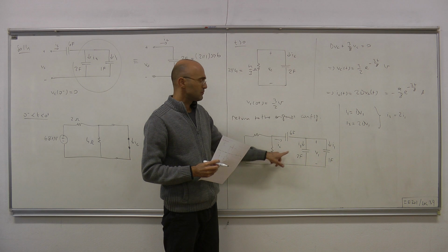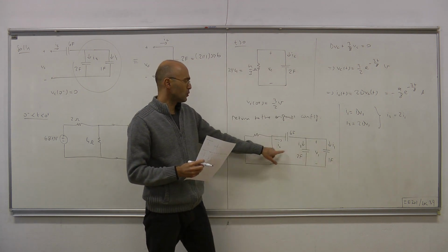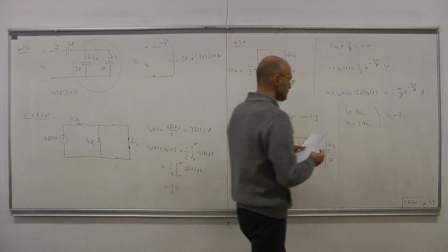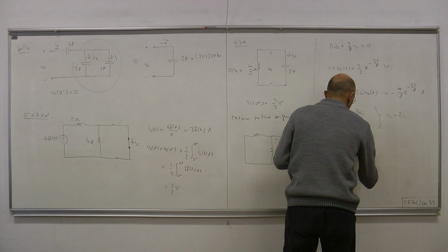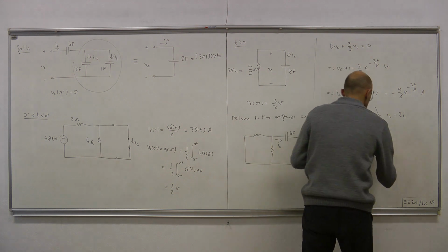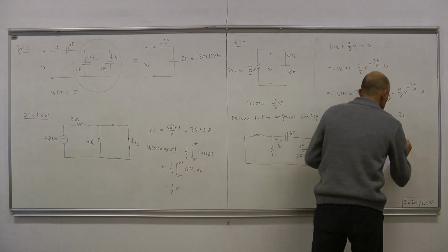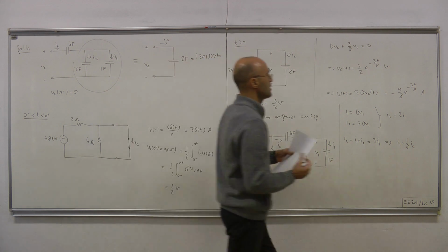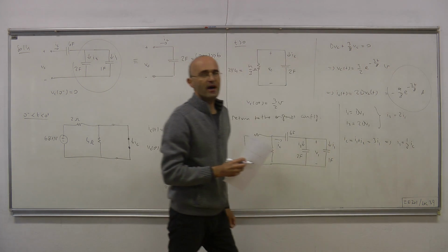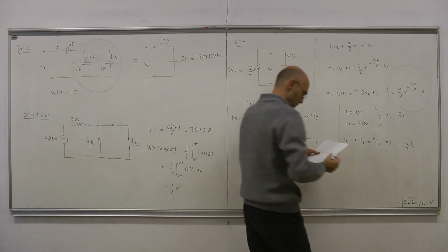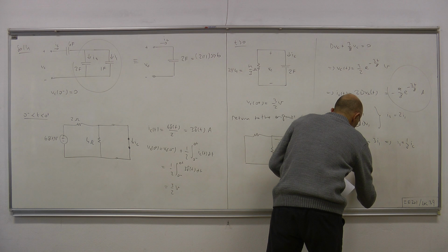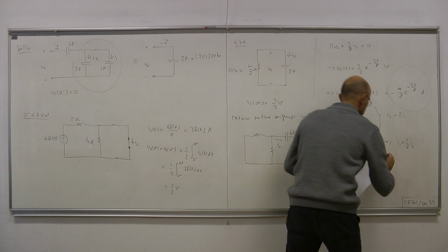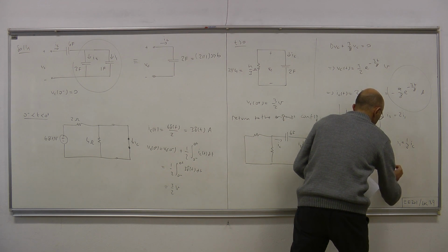And IC equals I2 plus I1, therefore IC equals 3I1, hence I1 is IC over 3. IC equals I1 plus I2 by KCL, that equals 3I1, and that yields I1 equals 1/3 IC. And IC is here. Divide that by 3 and you have your answer. I1 of t, therefore, must equal minus 3 over 8 e to the minus 3t over 8 amps.